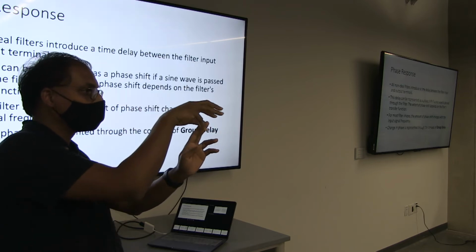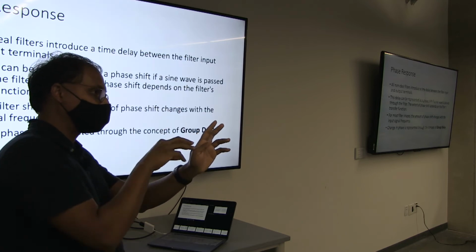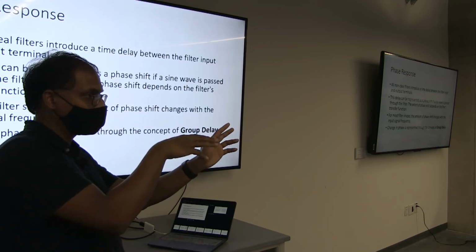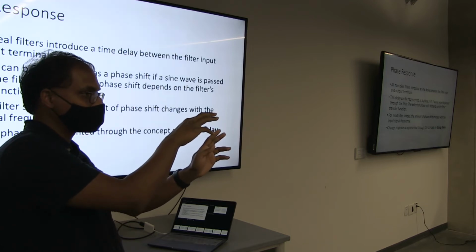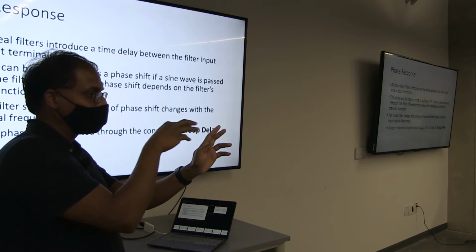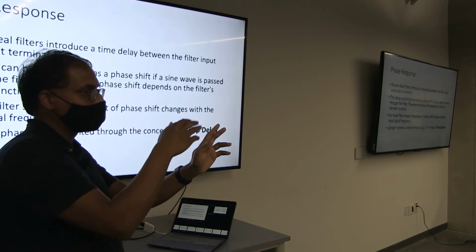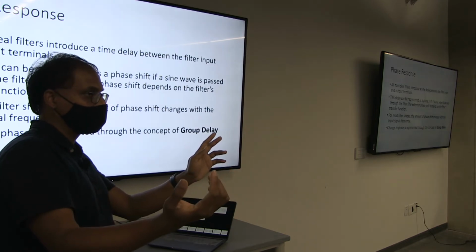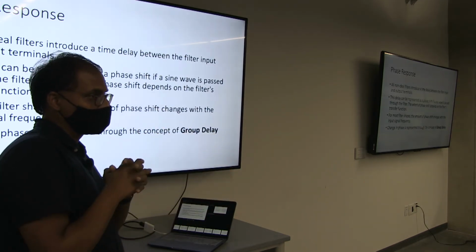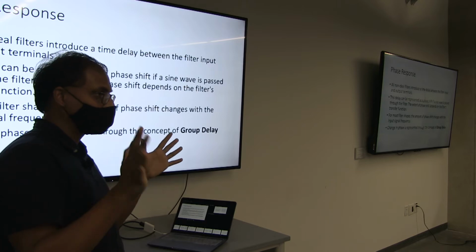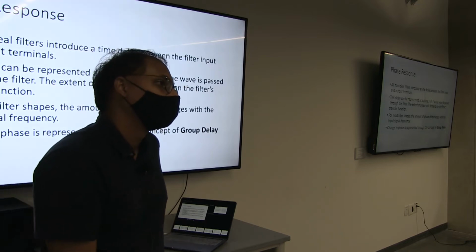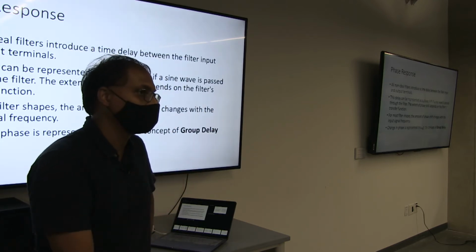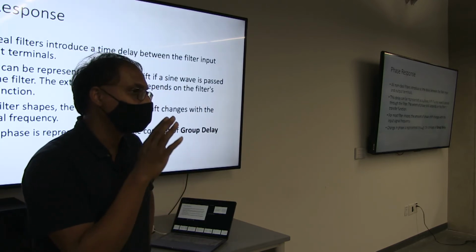So if you have 2 poles, then the phase shift at the pole is 90 degrees. So whenever you give a sin omega t and you have a 2 pole system, at the frequency of the pole, it becomes cos omega t as it comes out, because there is a 90 degree phase shift. Is it okay?